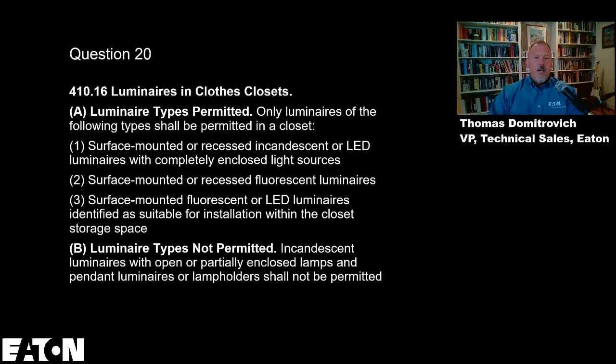So it's not required on everything, but you have to understand the location and its application based on the NEC. And I would review a few of the earlier questions on locations like in the gyms and sports arenas and in closed closets, those discussions from the previous questions, to help understand the answer to this question.